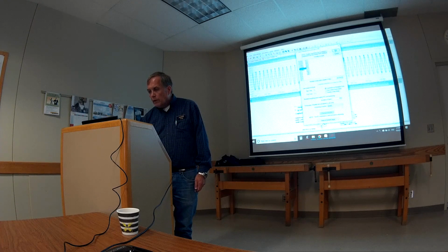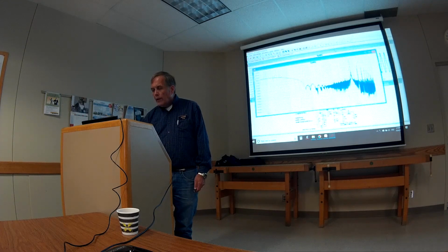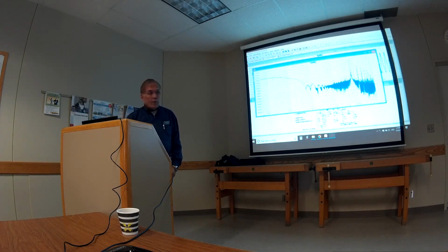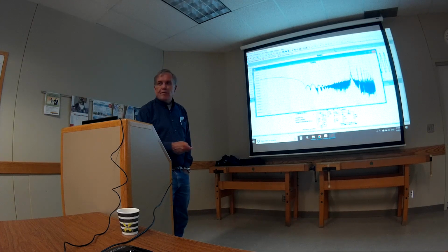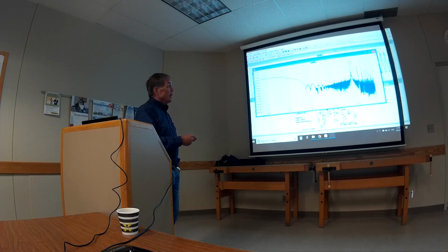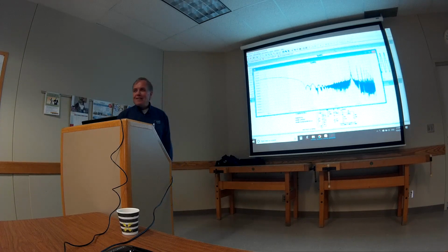There's only one view that I'm looking at right now, and there it is. You can see here's 10 megahertz. You know, the fundamental is right there at 7 megahertz. You can also see a nice spike at 14, 21, 28, and so on. These are harmonics that show up here because this is not filtered at all.